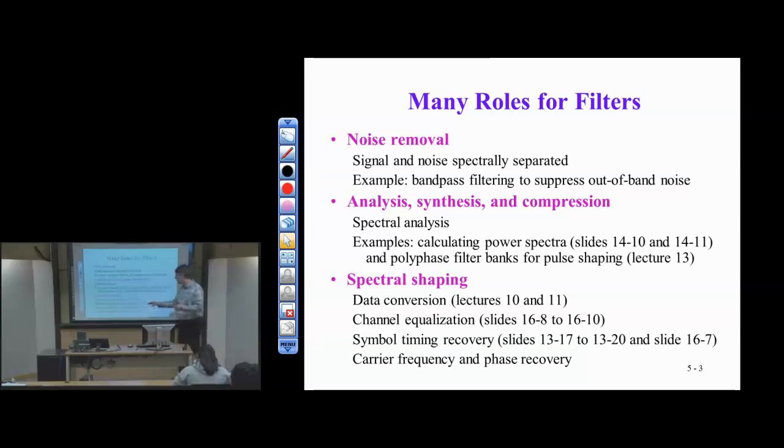On the receiver side, what we'd like to be able to do is make sure that the transmitted signal got through, and whatever frequencies we're using in the transmitted waveform, we would like the receiver to compensate for any distortion that happens in the channel. So the channel can be thought of as a filter. It could be low pass, high pass, bandpass. And the receiver is going to have its own filter to compensate. So if I have a low-pass channel, my equalizer would be high-pass, if I want to equalize overall frequencies.